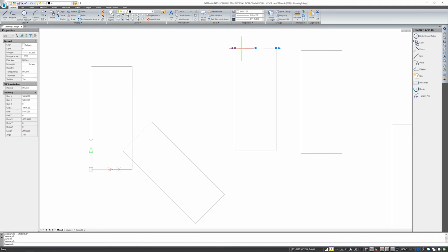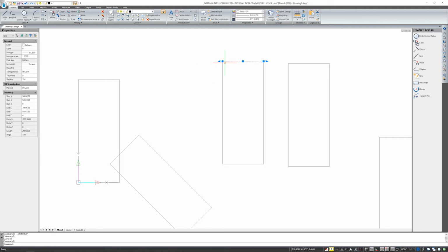After the selection, if you choose the properties, they'll be useful to you now. Then you can see that this is a line. Generally, in IntelliCAD, if you select any element, then the so-called handle appears on it. The handles are blue by default, but you can modify this. As for the line, these handles appear at the beginning and at the end. And in the middle, it shows us a handle that we can move the entire element with. So the beginning and the end will allow you to lengthen, or let's say curve your line. The middle handle, on the other hand, will allow you to move the entire line.